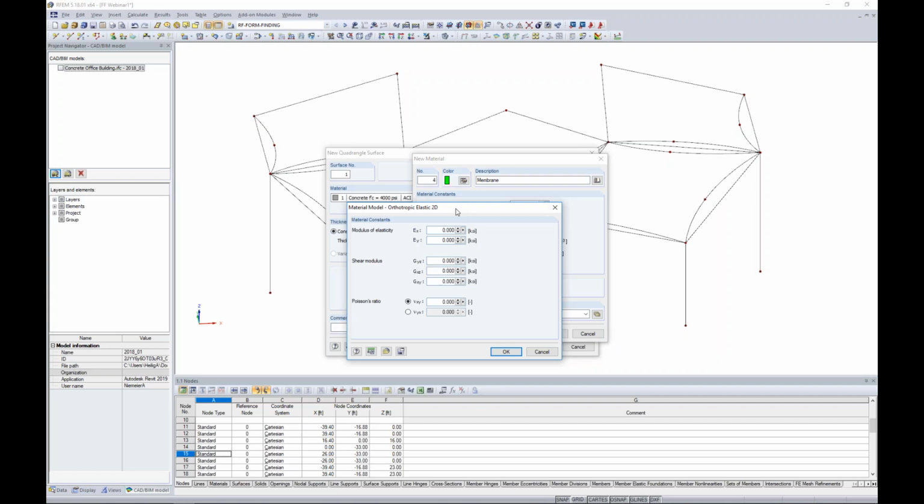For our example today, we know from our manufacturer that our fabric membrane is stronger in one direction than the other. But this is actually something that I'm going to set in as an isotropic membrane for the time being. The reason why is because I don't know, with these complex shapes of my membranes, complex geometry of the canopy, which way I should span that strong axis of my membrane to take the high tension forces. So I'll show you later on how we can easily determine that.